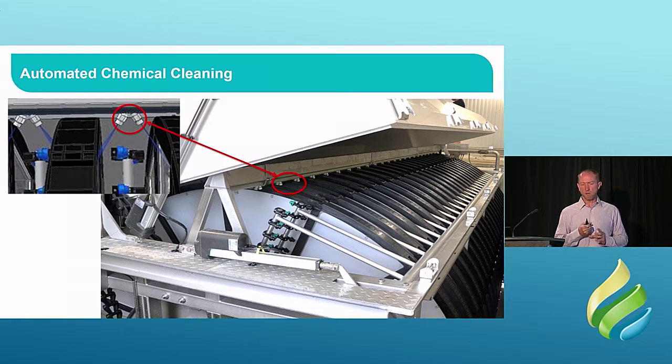So it's definitely a feature, and when I say very little, we put in a system recently, I'll talk a little bit about it later. It was a 25 megaliter a day plant, design flow for the filters, and there we were talking about less than $50 a year in chemical cleaning costs, the chemicals, less than $50 a year, so next to nothing.